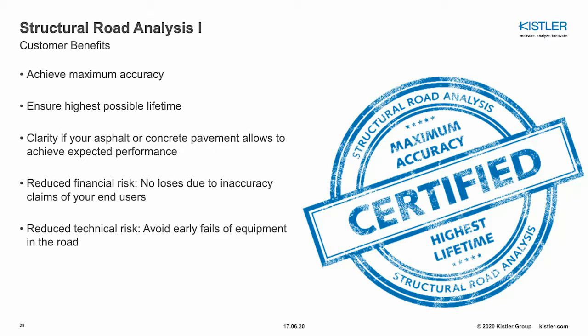In order to do that, it is highly recommended that you order a structural road analysis before the installation of the system. It gives you clarity about your asphalt or concrete pavement conditions and whether you are even able to meet the requirements of the end user. It will reduce your financial risks if you cannot hand over the site to the end user because of low performance or bad accuracy, and it will also reduce technical risks, meaning early failures of the equipment in the road.